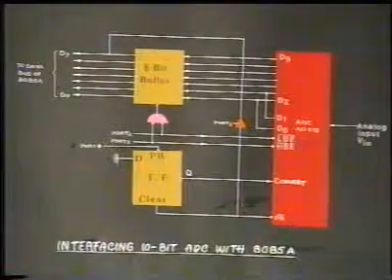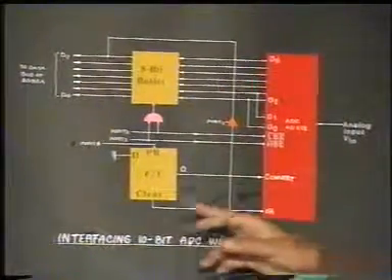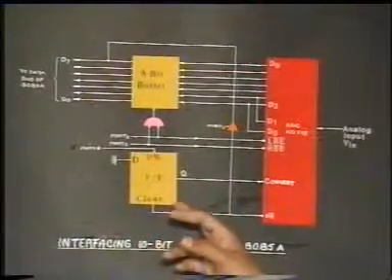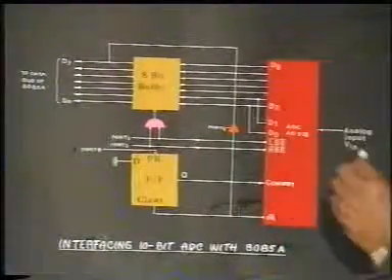Again, the status check approach has been applied here. We give the start of conversion signal to the convert line here. This can be given by setting this flip-flop active high by some port enabled by the microprocessor. When the convert line goes high, that is the indication of start of conversion.